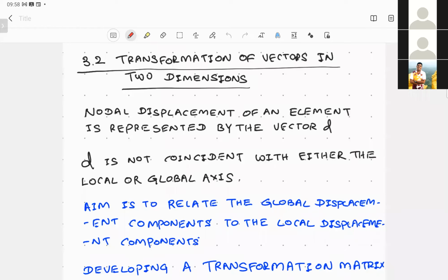So the road which we take from the element stiffness matrix to a total global stiffness matrix is, first you get the element stiffness matrix for a single element or for all the separate elements you have in the system, and you try to construct the global stiffness matrix for a total structure.